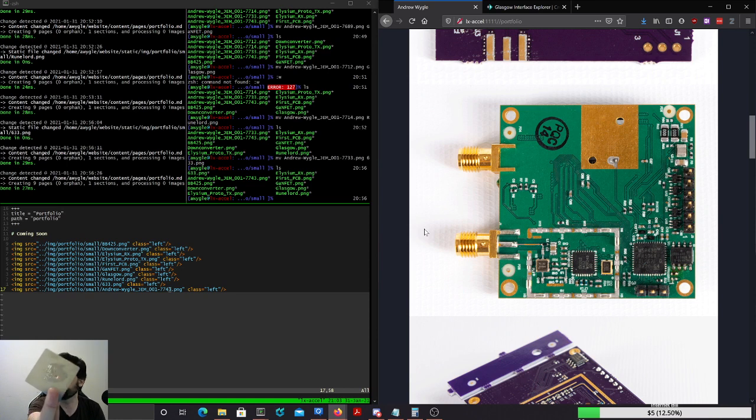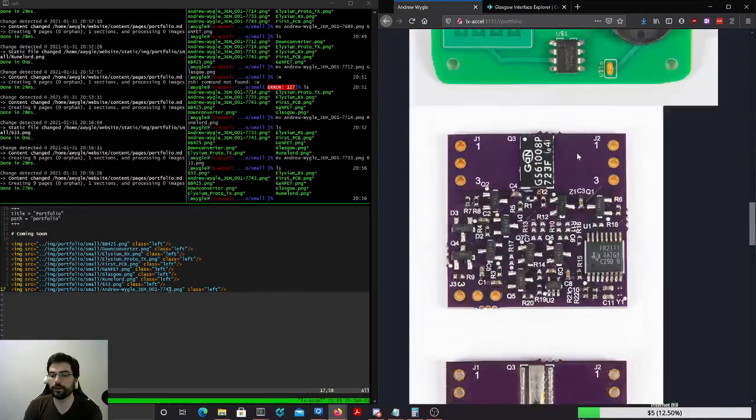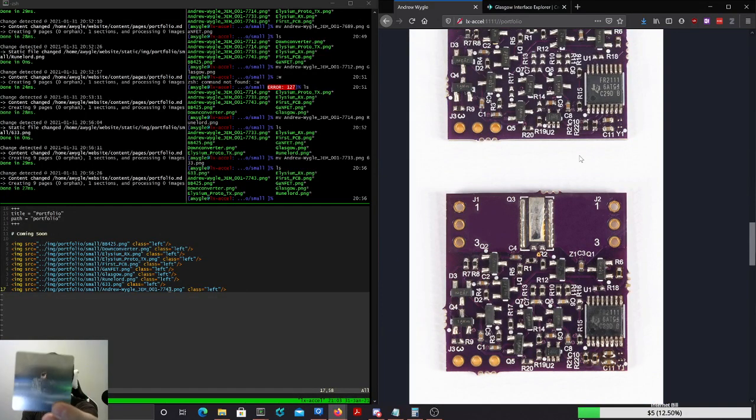Yep, exactly. So this is a stainless steel soldering stencil. What you do is align it with the pads. So this one, let me pull up the right board here. Okay, so this one matches that. Again, I still have no idea how much you can see, but it has the same openings where all of the solder pads go.